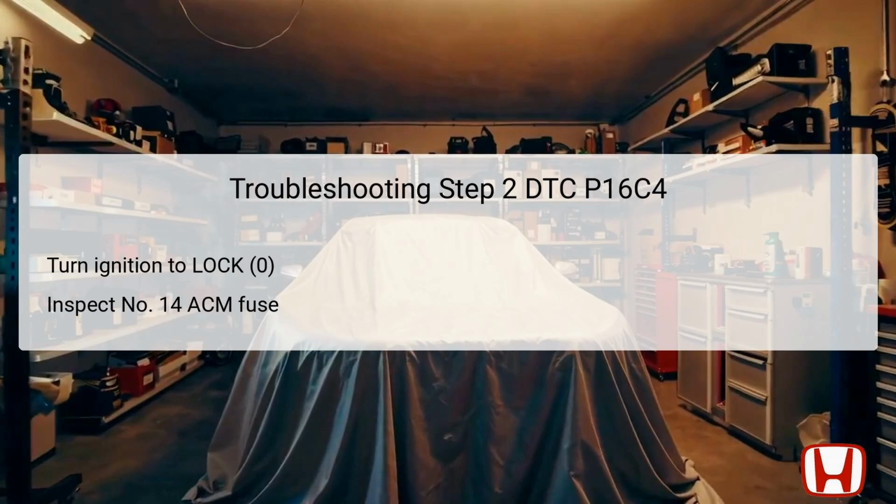Checking the status of the fuse involves visually inspecting it to see if the filament is intact, or using a multimeter to measure continuity. If the fuse is okay, the focus then shifts to other components in the circuit.